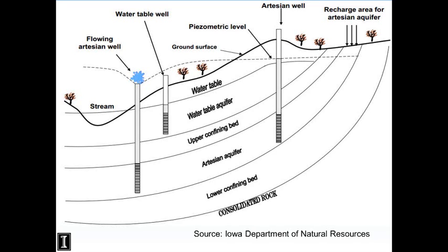If you lift up both ends, you can regulate how much water's in your hose by how high you lift it. And once you have water higher than the top end of the other hose, it'll come out, which is the same thing as a flowing well, an artesian well. And so here, this is the water pressure level. It's called the piezometric level in the deep aquifer.